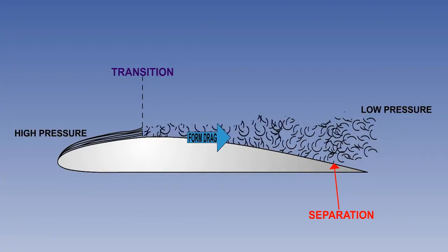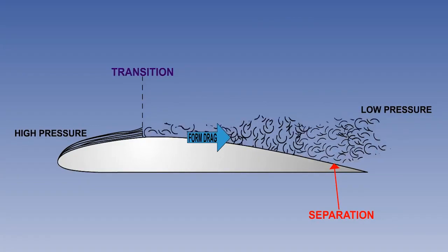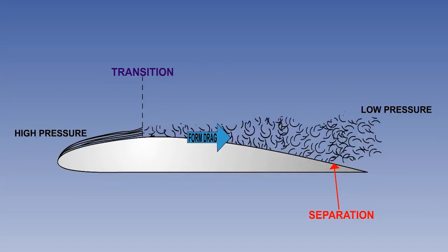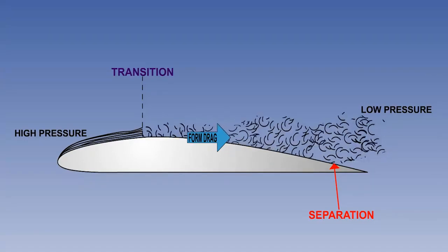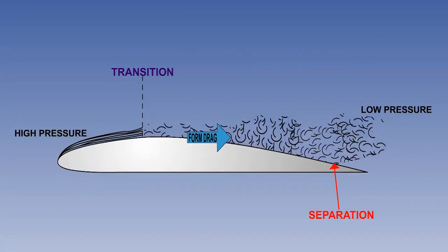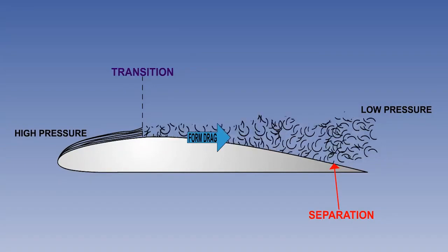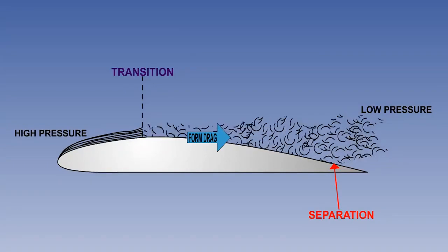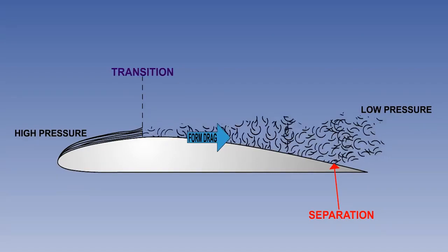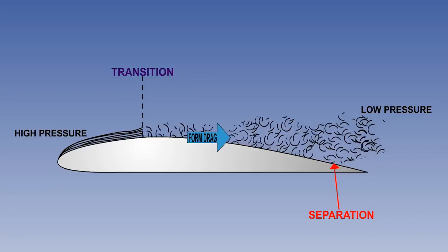The surface flow after the separation point will now be forwards, but because of separation, there will be a lower pressure at the trailing edge than at the leading edge. The aerodynamic force from high to low pressure thus acts against the direction of flight as form or pressure drag. The loss of the kinetic energy required to overcome the adverse pressure gradient and prevent separation of the boundary layer can be caused by various factors.